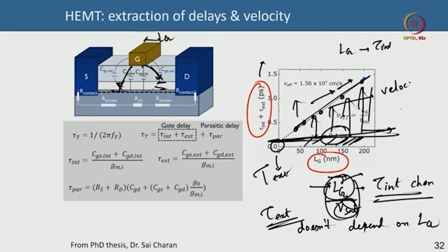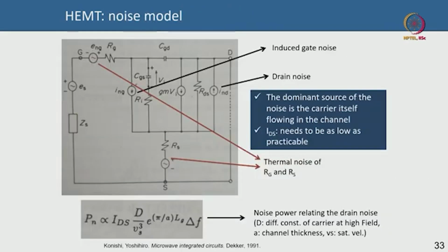It is a very laborious, long process. However, the last topic that we are going to discuss in baseline InGaAs HEMTs is the noise model or the noise performance. What I am showing here is the noise small signal model of an InGaAs HEMT. It looks almost identical to that of a MESFET, if you recall. Here you can see this is your gate drain capacitance.